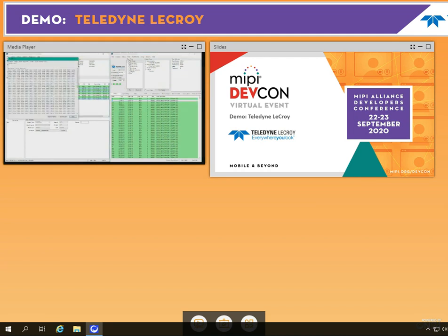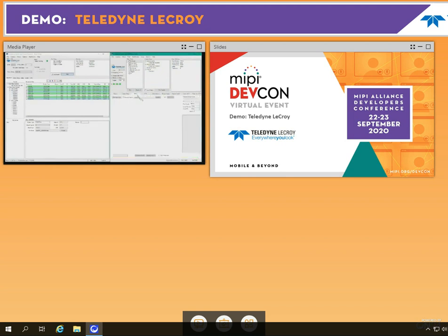Double-clicking on a packet brings up the actual data payload of the packet, in this case the actual pixels. This data payload can be saved or appended to an external file for offline analysis. Moving over to the Video tab, the Envision X84 can play back the captured images. During the playback, it will display the detected image format, the resolution, and the RAW format.